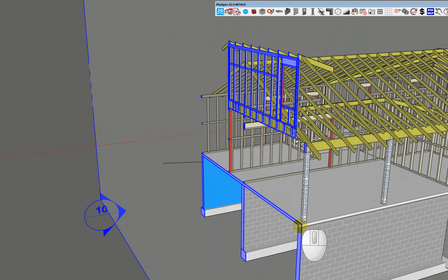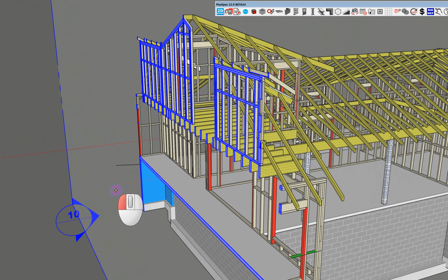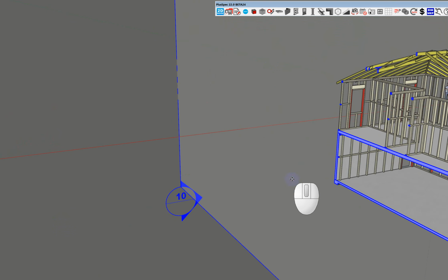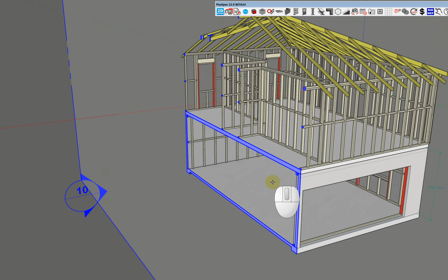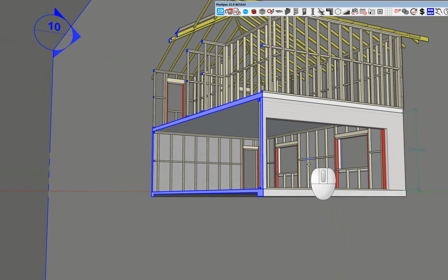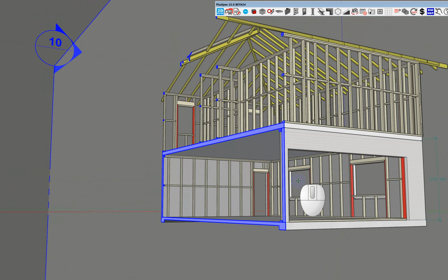Now, also the slab in this particular area, or all of this front area, it seems as though you can get away with a 100mm slab to hold up all of that area. However, when we get to the garage, I would go 150 there with Bondec. I actually have Bondec drawn in there, and I think that's going to help out a lot, getting this stuff sorted out.